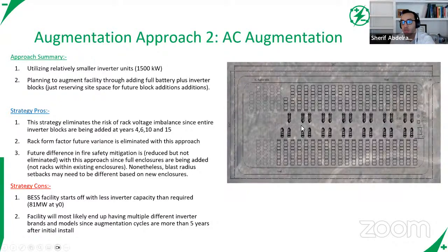So physically, you would build the medium voltage collection system such that it has capacity for all the future phases you plan to add. You'd also account for that additional power capacity, again for all phases, in the GSU capacity, so that when you add more PCSs, you don't have to upgrade your GSU if it's transmission tied.